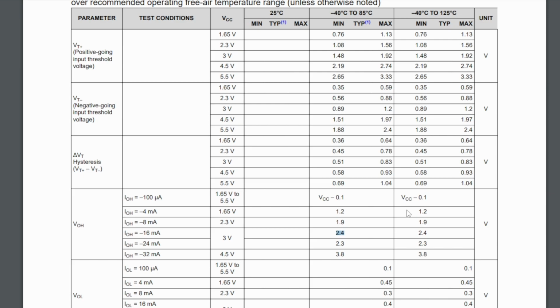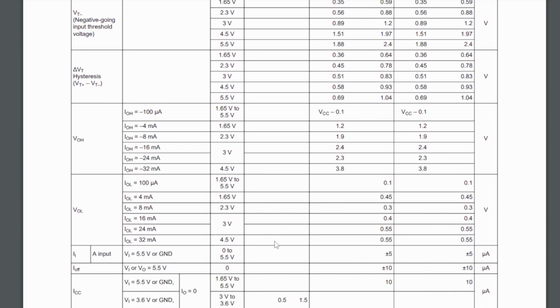So that 37.5 ohms is also the worst case. And in this case, worst case means higher resistance. So technically, you're going to see a lower resistance than that 37.5 that we just calculated. And in fact, if you run across the majority of logic datasheets, you're going to find that the typical value is half. 18 or 19 ohms is much more likely to see than 37 or 38 ohms.